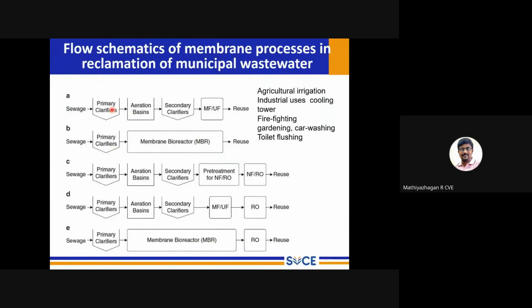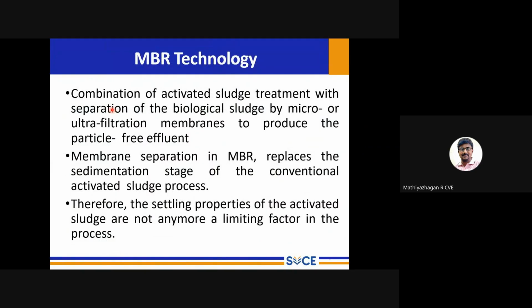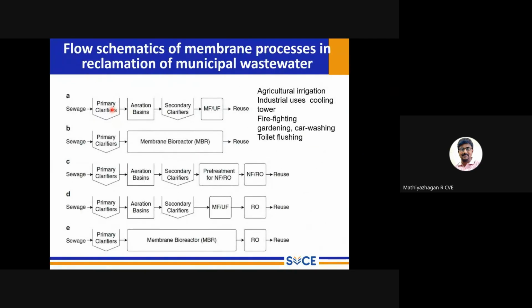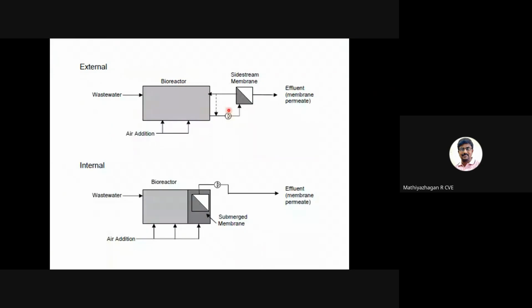And MBR technology is also available. It is a membrane bioreactor. After the secondary clarifier or sometimes the aeration basin, we have the membrane process to remove all kinds of suspended matter. It may be provided externally or internally along with the bioreactor.